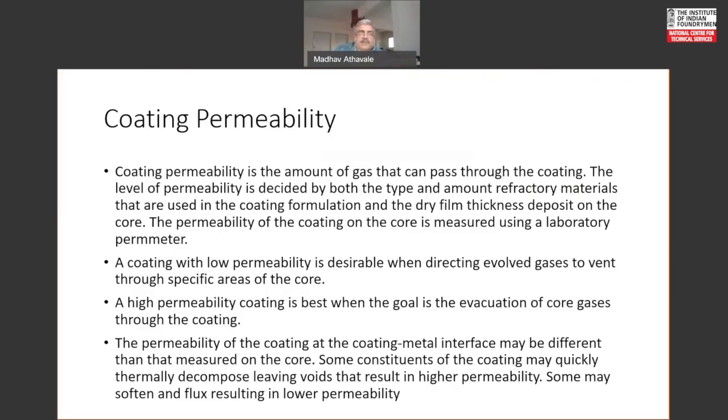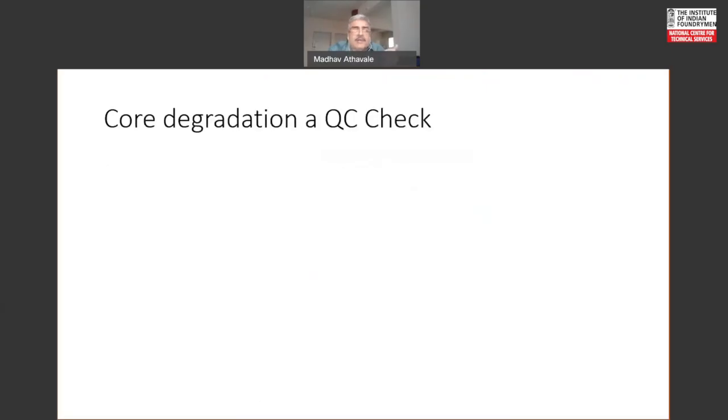What one should remember is permeability of the coating as tested on say a 2-inch by 2-inch core in the laboratory by using permeability meter at room temperature could be different than at high temperature, because there will be a degradation of the coating layer.